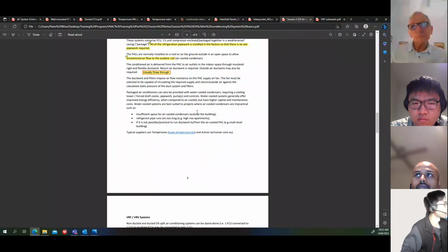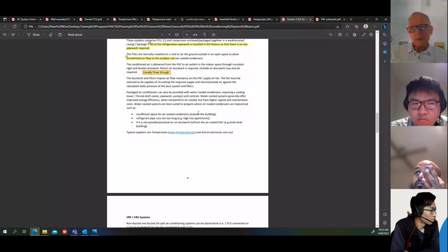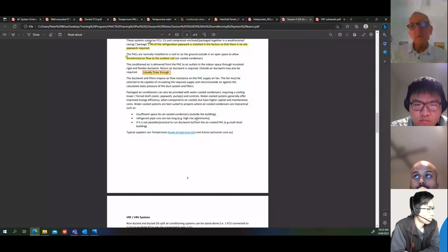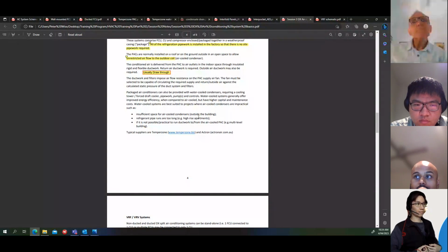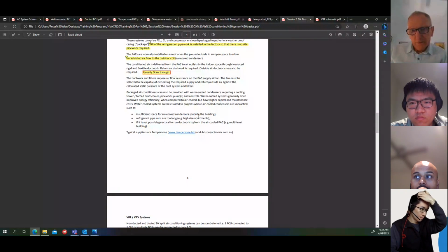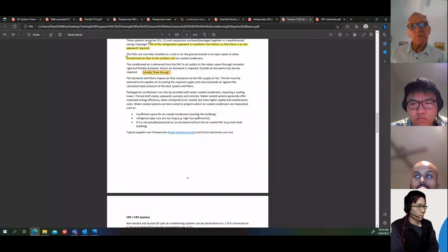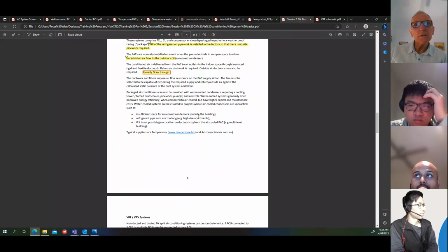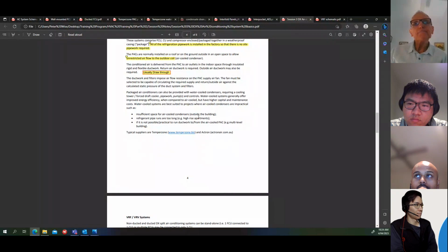One job that comes to mind was done a long time ago. I was involved in it. It was a university building, and they wanted individual control in every classroom, every workspace within this new building at the university. In those days, actually, VRF didn't even exist. So the only option we really had was to go with either a chilled water system and have chillers and probably a water boiler, obviously a cooling tower.